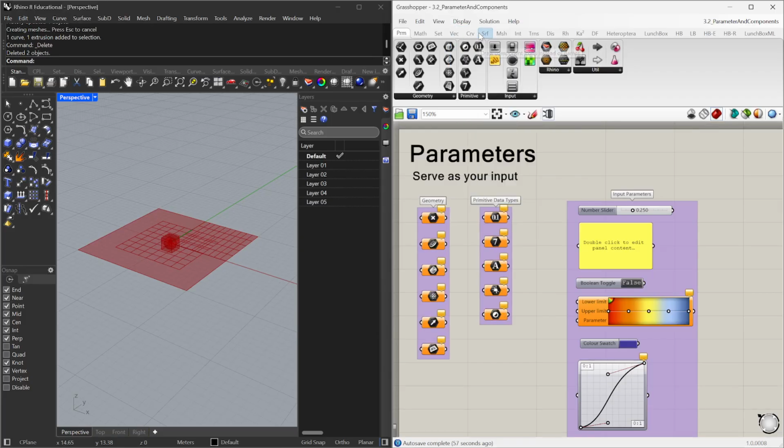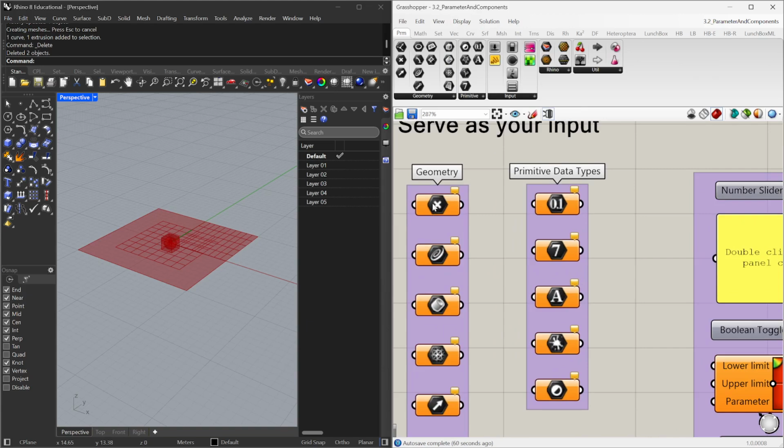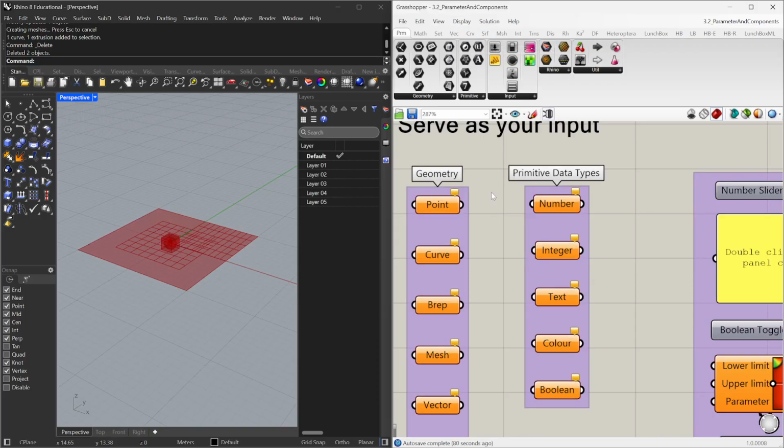The different displays are here, and I'll show you how we can use them and what they mean. If I do draw icons, it will draw an icon instead of having the text. Now, when you first start out learning Grasshopper, I recommend that you keep the words on there and let it tell you what is in there, just so you remember. Because sometimes it's hard to remember just by a graphical icon exactly what it is and what it does. So if you wanted to change that, you can go up here to display and turn draw icons off and it will replace it with the words. And then you can follow along a lot more easily.